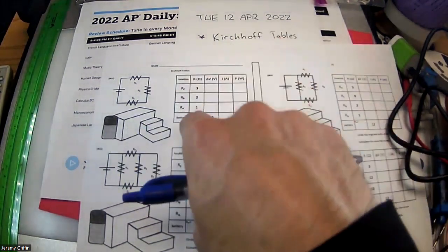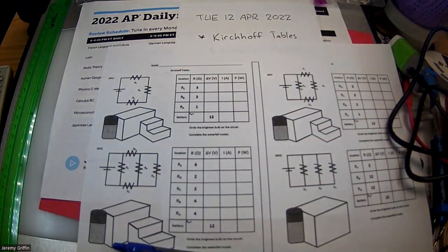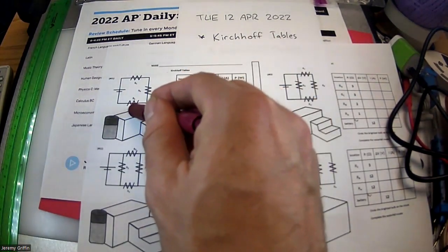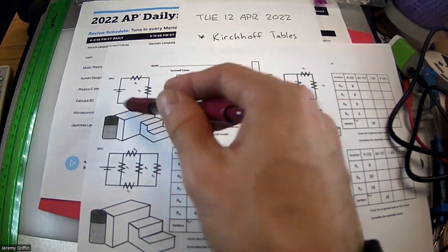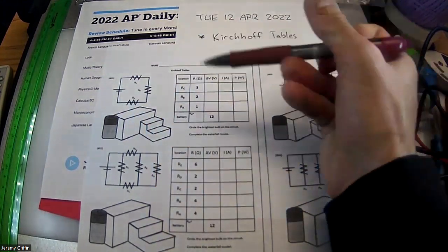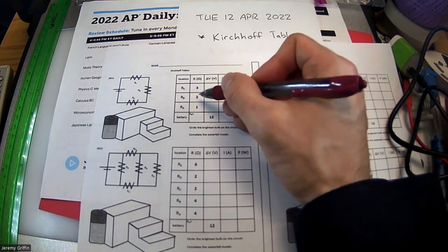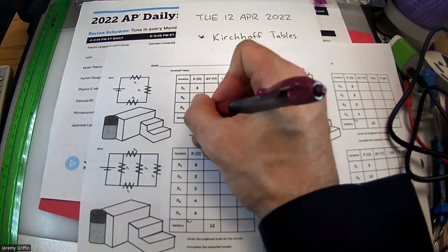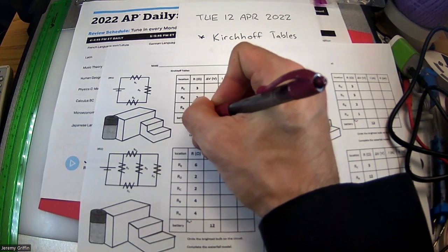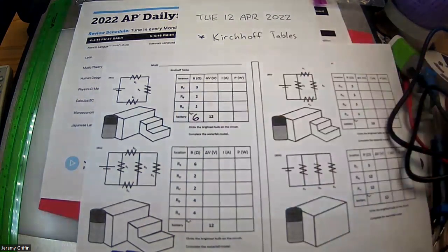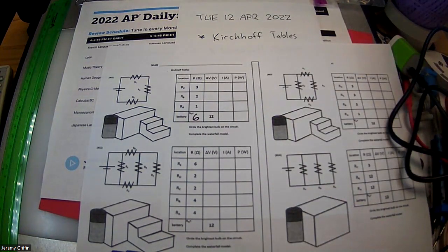So start with the equivalent resistance. Now, because these 3 are all in series, can I just add them up? That's exactly what we're going to do. This 3 ohms plus 2 ohms plus 1 ohm gives me 6 ohms equivalent resistance. So the battery feels like it's pushing against 6 ohms, well, on my paper anyway. An analogy you can make here is that solving these Kirchhoff tables is kind of like solving a Sudoku puzzle. Once you have a certain number on the board, then everything else is determinable.